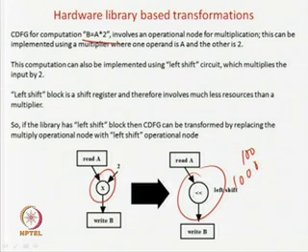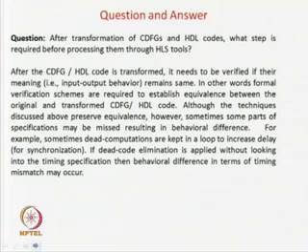So these types of transformations are possible only if you have some specific component in your library which helps your optimization, by not using a general purpose comparator, general purpose multiplier, or general purpose adder. For some specific cases, other circuits are available which you can use.